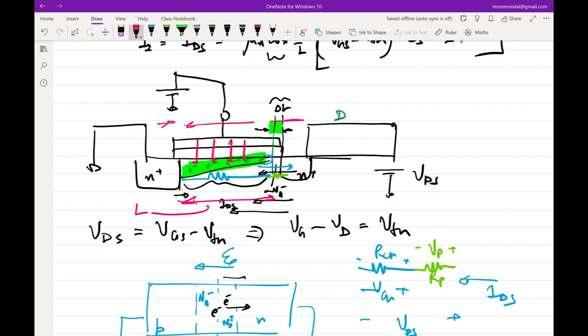Similarly, there is a constraint on the thickness of the oxide that you can apply, because if you decrease the thickness, naturally you are increasing the electric field, which means the maximum voltage that you can apply between the gate and source is also limited, because you might end up in breakdown, right? One reason you would want to reduce the oxide thickness is that you get better gate control.